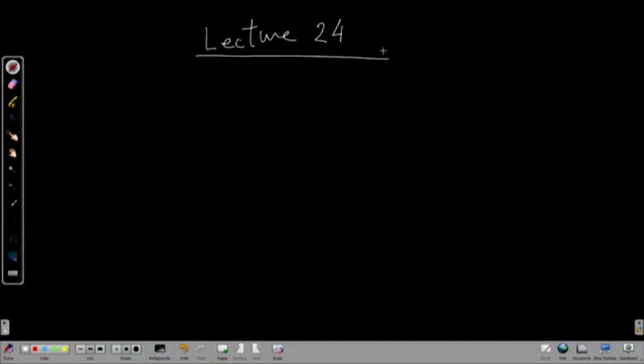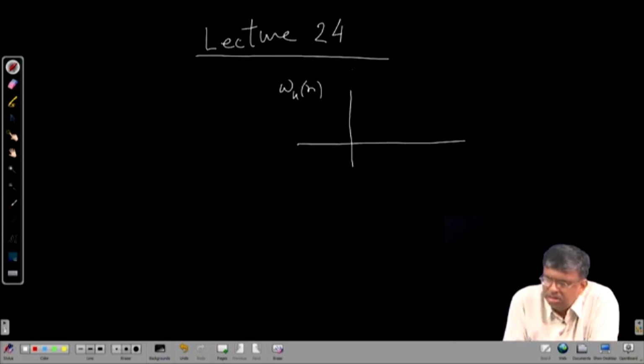Okay. So, we had seen earlier that in the LMS algorithm, the filter weights converge not absolutely, but only in mean to their respective optimal values as the iteration index small n goes to infinity, that is, we reach something called steady state, that is, for large values of n. Typically, if you take any kth weight, we had already discussed this, I am just repeating.